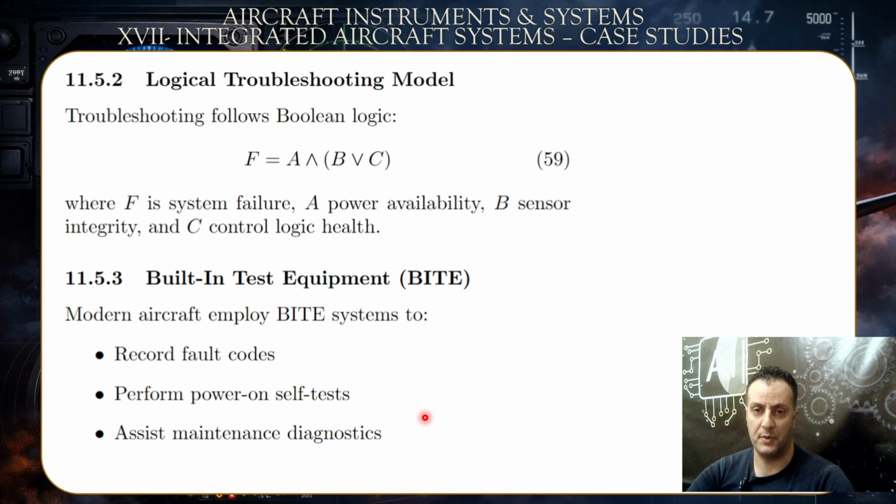They would open up. Okay, now third, to assist in maintenance diagnostics. The BITE system is necessary to assist in diagnostics, to understand what kind of faults have occurred or are occurring during the flight or during ground operations, okay, during ground maintenance.